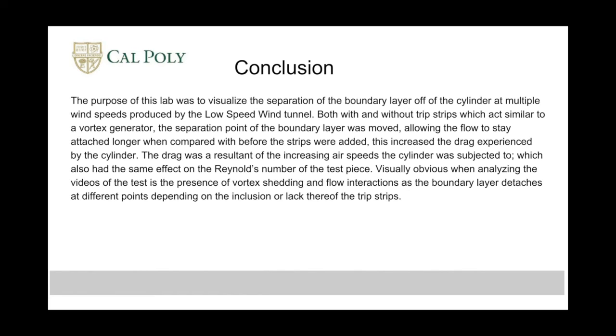Visually obvious when analyzing the videos of the test is the presence of vortex shedding and flow interactions as the boundary layer detaches at different points depending on the inclusion or lack thereof of trip strips.